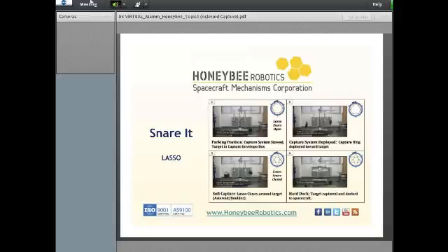Where we're at a standoff distance, and between 1 and moving to the top right, number 2, our snare system is deployed, and it's deployed in this demonstration via a series of carpenter tapes. But we envision a little higher stiffness system in future development using some graphite roll-up beam assemblies that we've worked with a partner of ours on for deploying large solar arrays. But the stowed to deployed ratio of a system like this could be very large. So the standoff distance could be quite large.